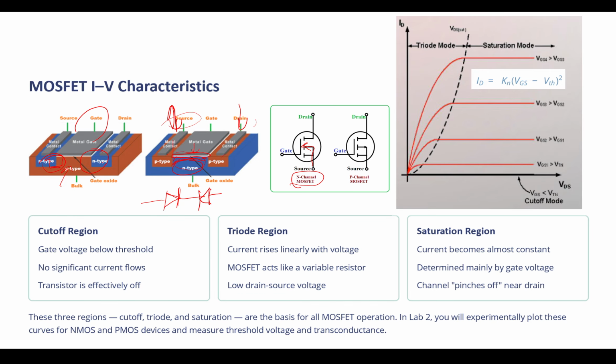And as much as you increase the voltage between the gate and source, the width of that channel that you created would increase and increase all the way to a certain point, which we call the saturation point, which is the case that you have enough voltage between the gate and source that you already made the whole channel polarized. There is no more capacity for ionization or polarization of the material.